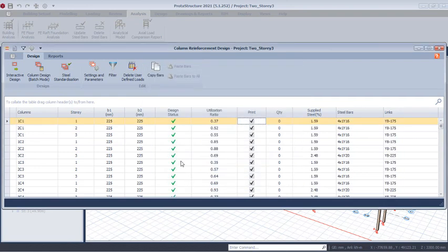To see all the columns that have been designed, the links are at spacing 175. You can see there we still have members of 4x16, and then some columns are 4x20. You can see over there 4x20. There's even a column carrying 4x25. All right, so you have to take note of all of these columns.